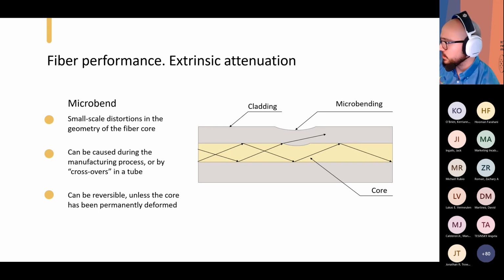If a connector end was bad on a fiber optic, would it be possible to repair the connector instead of replacing the entire cable? Yes, absolutely. We do it all the time with our OTDRs. The connectors go bad, we have to cut them back and put on a new connector. So it's very possible just to replace the connector if that's what's going wrong with your cable.